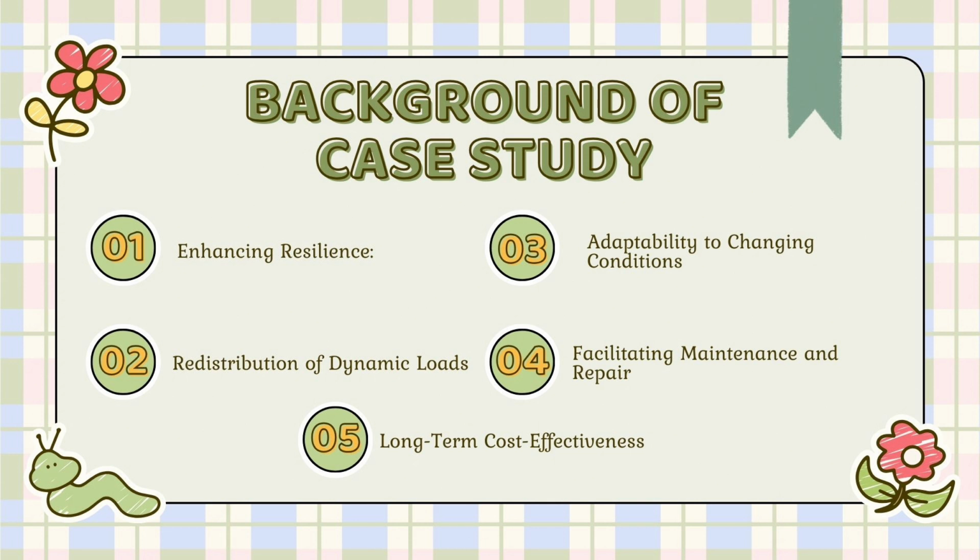As critical components of transportation infrastructure, bridges must endure dynamic and varying loads, including vehicle traffic, wind, and seismic force. The incorporation of K-truss into the bridge addresses this challenge by providing redundancy, ensuring stability even when certain members are damaged or compromised. The dynamic nature of bridge loads requires an efficient distribution mechanism to prevent localized stress concentration.